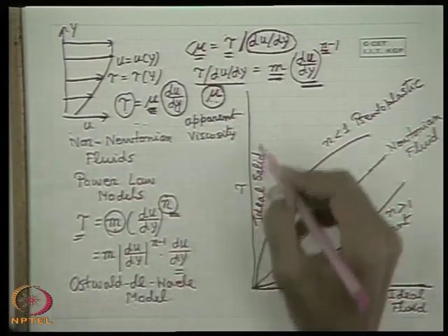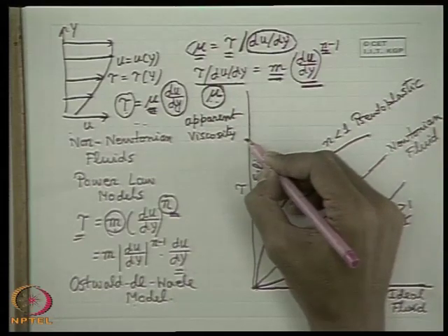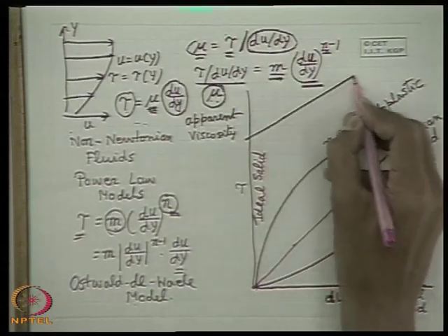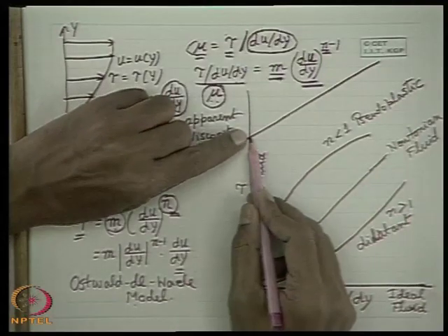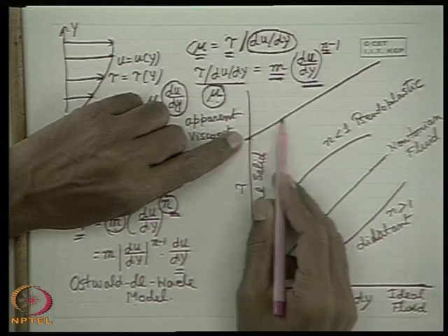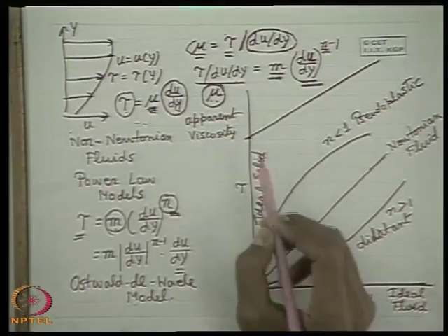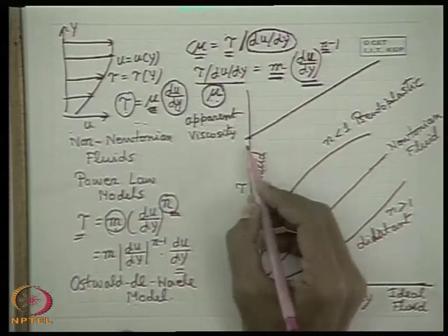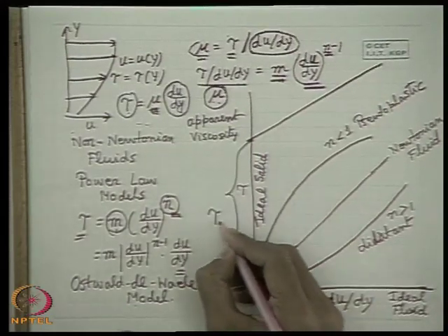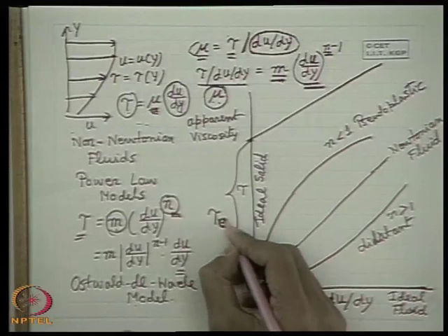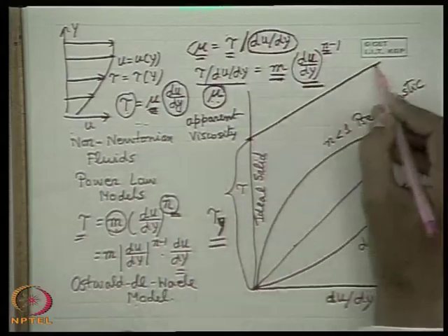Well, another class of fluids occurs in nature, and they behave like this: a definite amount of stress is required to cause the motion. That means the flow takes place only after a definite stress is applied to those classes of fluids or substances, and this stress value is known as the yield stress, tau Y. This is known as yield stress, after which the flow takes place.